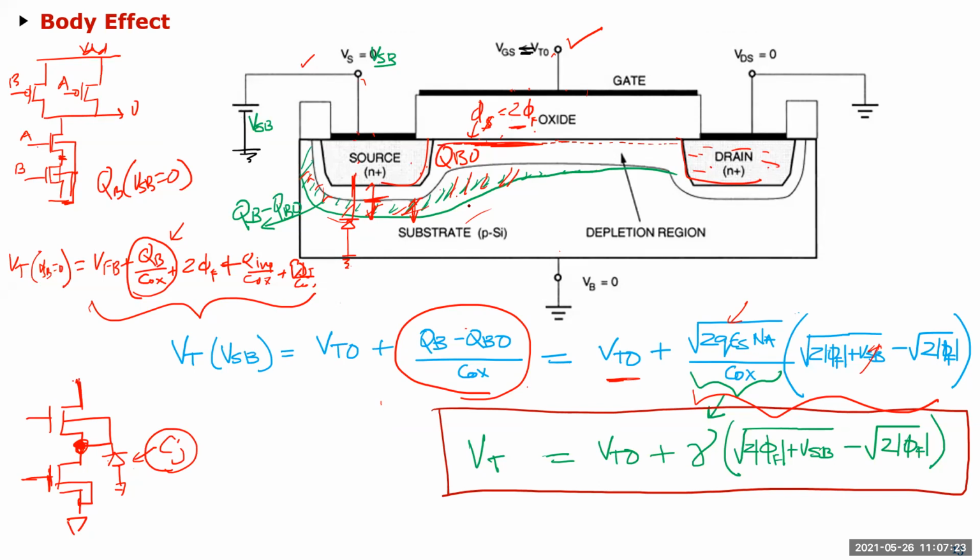But what I see most people do is use the SPICE simulator to design. You don't want to use the SPICE simulator to design. There's a derogatory term in IC design, we call it SPICE monkeys. You don't want to become a SPICE monkey who's just pressing buttons and trying to get some results. So these level 1 models are still very good, because they'll get you very close to the accurate result, and then you use the simulator and tweak whatever you need. And not only that, if you have any problems or issues and you don't have a deeper understanding of what you're doing, then you would just be pressing buttons again in the simulator trying to get it working.